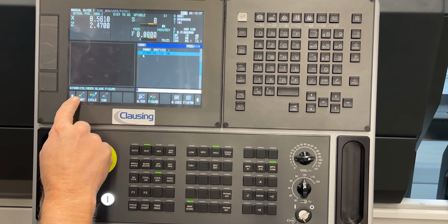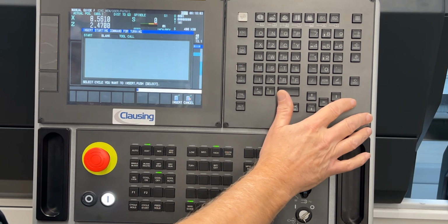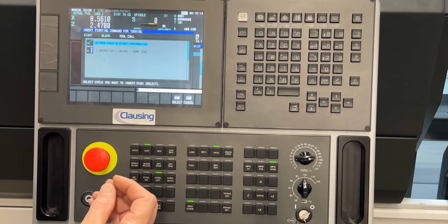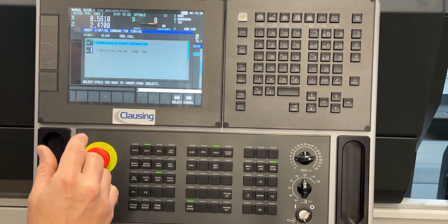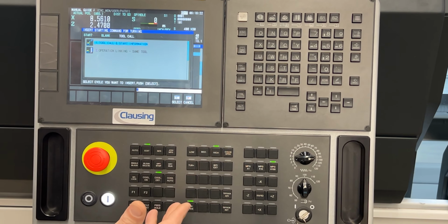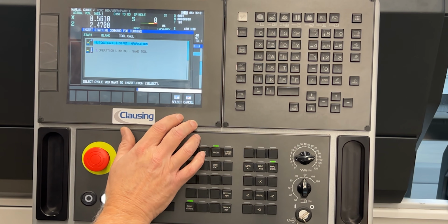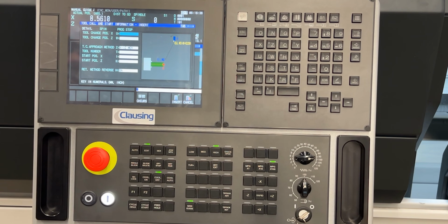And then I'm going to come back to the start menu again, and then go over to the tool call. Now this tool call has been created by Colchester Harrison. The tab was done by them, so you didn't have to type in G-code. Normally, in Manual Guide i, you would have to put in G-code callouts and the M-code callouts to activate the tool and the spindle and stuff like that, and to do movements, to get back and forth from the tool change position. They developed this so it's filling in the blanks.